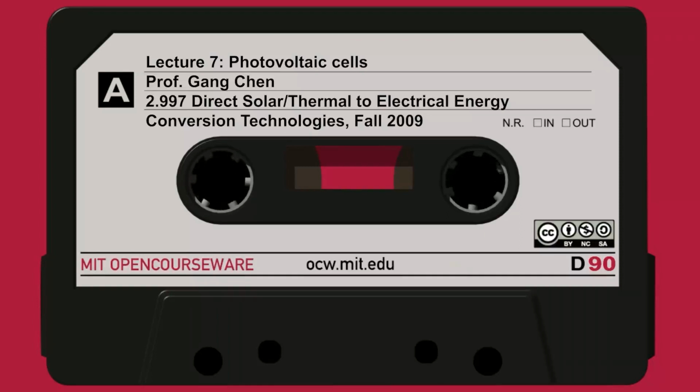Now, this is the potential hill for the hole, and this is the potential hill for the electron, going down there. That's the natural tendency. And because of this, you accumulate more electrons on this side and more holes on the other side. Normally at equilibrium there's no voltage, but now you generate a voltage. And once you generate voltage, this voltage will drive your diode. Just like on this side, if you have a voltage difference, you'll have a diode current here.